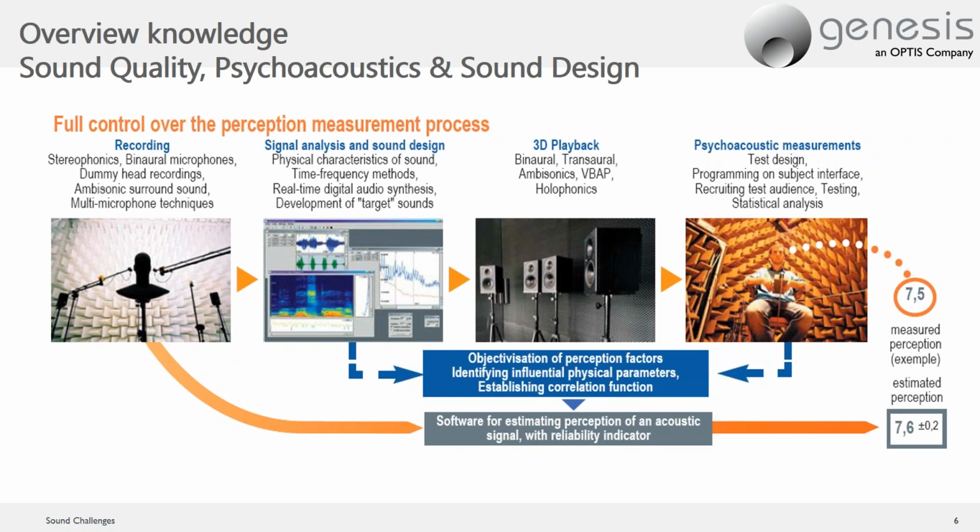So we can record that as one sound, then play it back in our software and actually visualize the two separate sounds inside of that. So we can remove the wind noise and just focus on the orders of the engine.